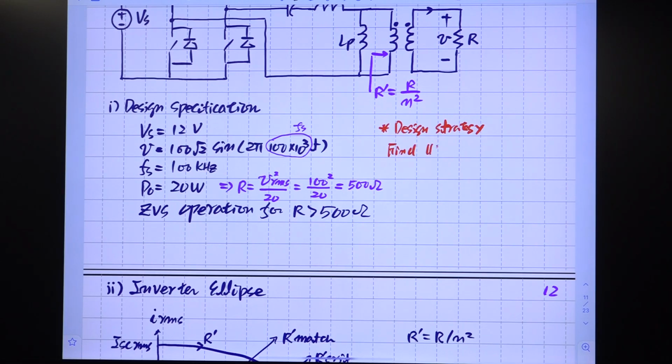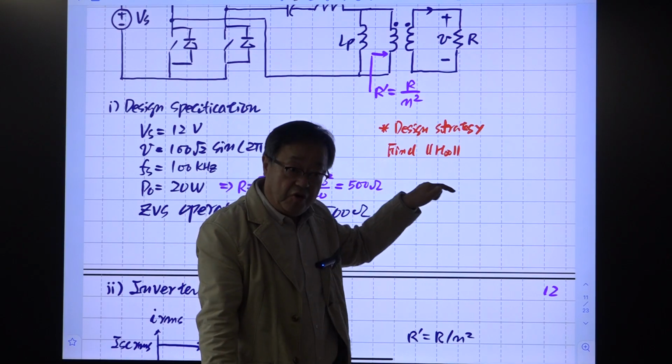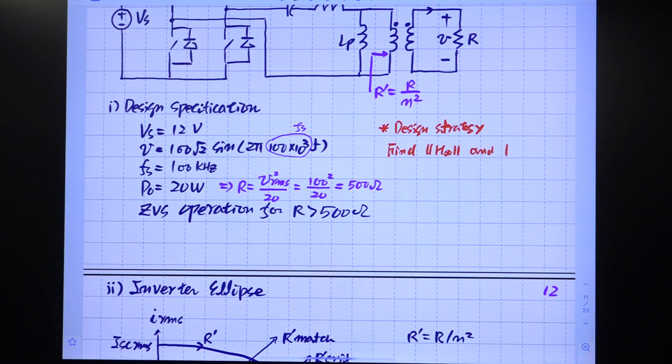Find this one. This is a transfer gain of tank circuit with output open. So this comes as the first parameter for your Thevenin's equivalent circuit for your converter or inverter, and find out this one, GO output impedance, evaluated with input port shorted.